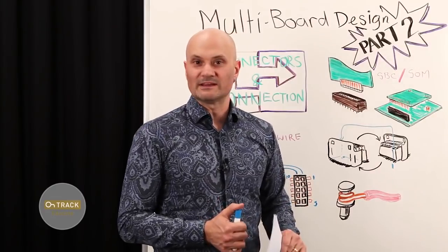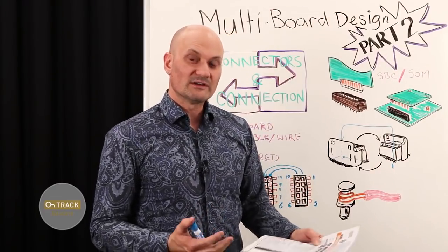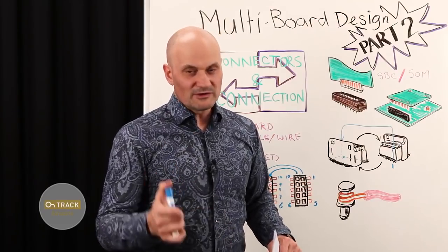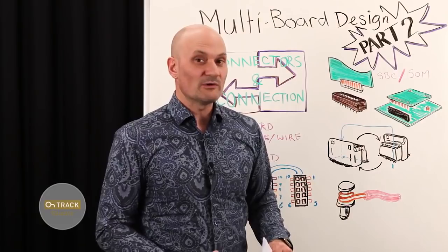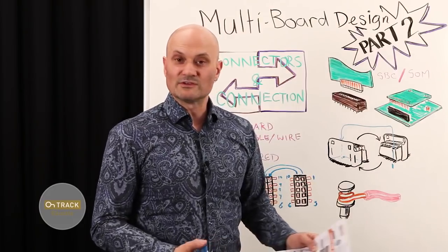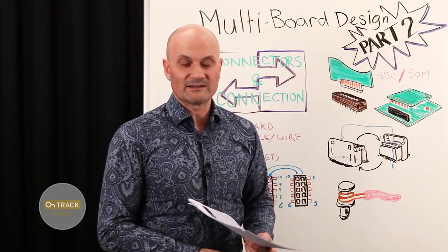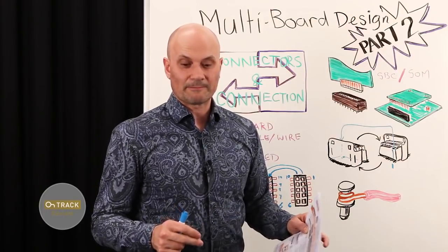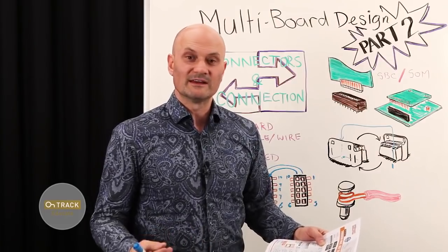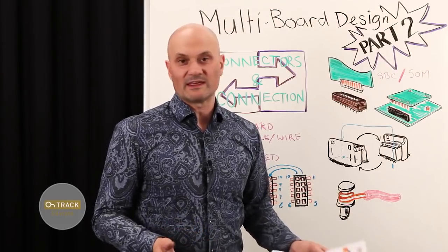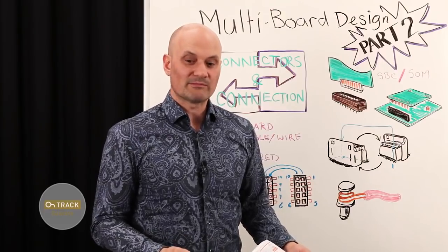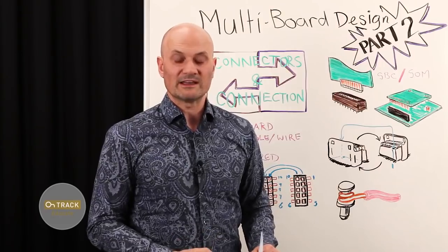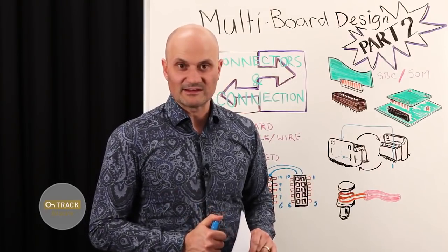It's awfully tempting sometimes to find an alternative source of these connectors on the grey market, and they're a lot cheaper. But if you do that, be warned, you need to get a few of them into a lab first and do some flame testing, do some testing with a hot air gun, and do some testing with some power supplies and loads and multimeters to make sure that their contact resistance isn't going to be a problem and that they can actually meet your current handling requirements. Sometimes the only way to get the data you need is to actually test it.